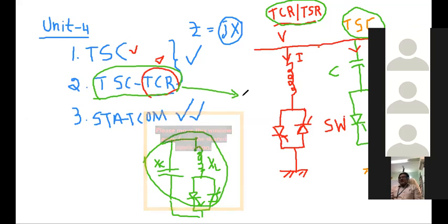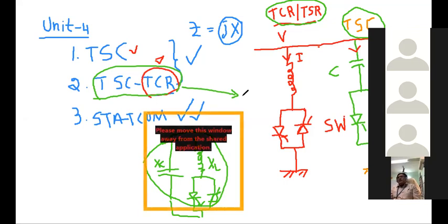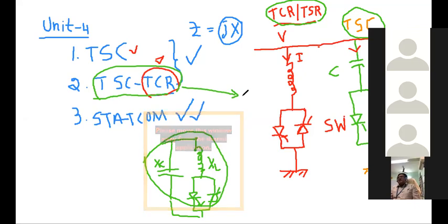And if you change the speed, then what will happen? Real power flow is either absorbed or sent to the mains. So exchange of real and reactive powers takes place once you change the excitation and once you change the input power to the alternator, either decrease or increase, and the excitation also increase or decrease. So real and reactive powers. Okay, and how it absorbs or supplies reactive power depends on excitation.